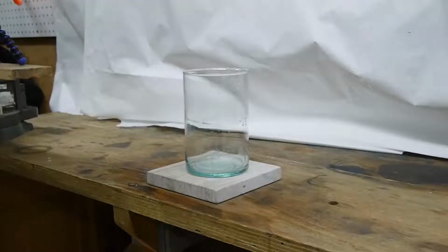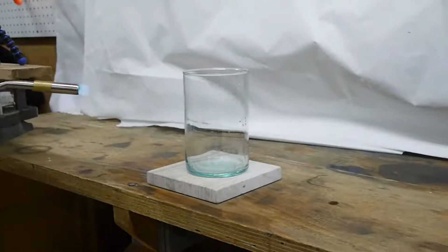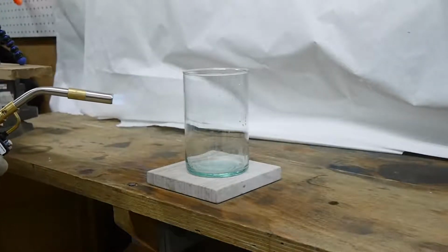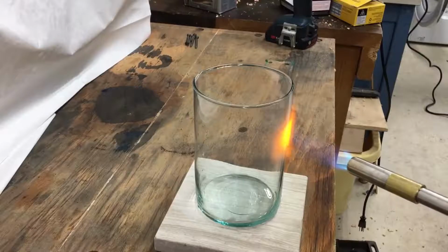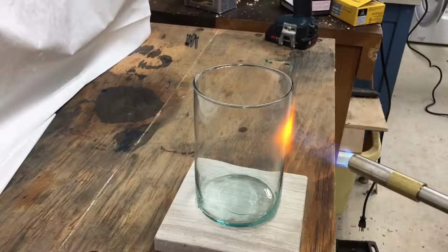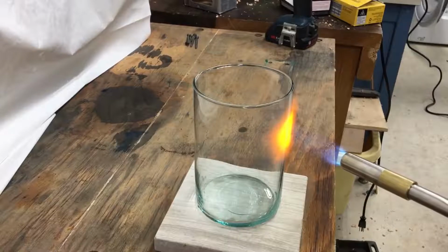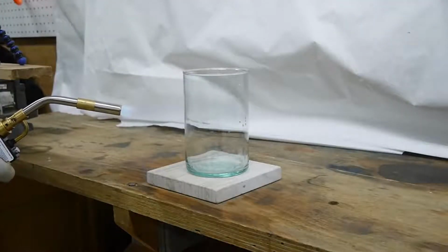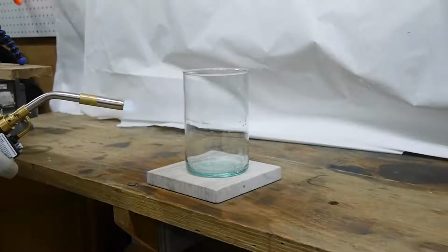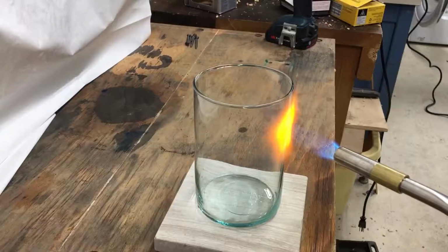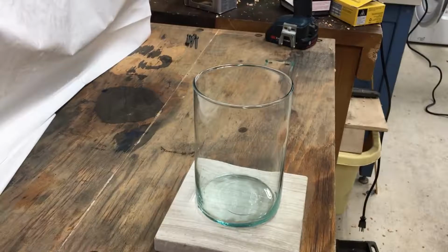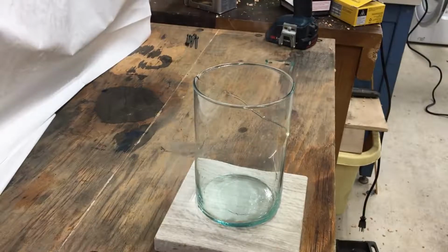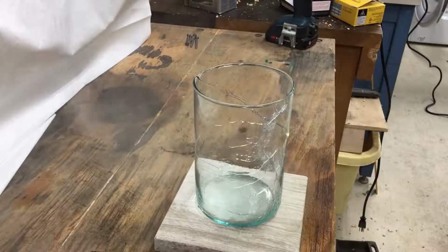Maybe you've had some experience with a less useful application of thermal expansion. If you've ever put glass dishware on a burner or poured cold water on a dish that just came out of the oven, you know it doesn't go so well. If it's allowed to expand and contract evenly, stresses in the material don't build up. But if you heat or cool it unevenly, certain parts of the glass will fight against each other as they change size. Glass isn't flexible, so instead of bending, it just shatters.